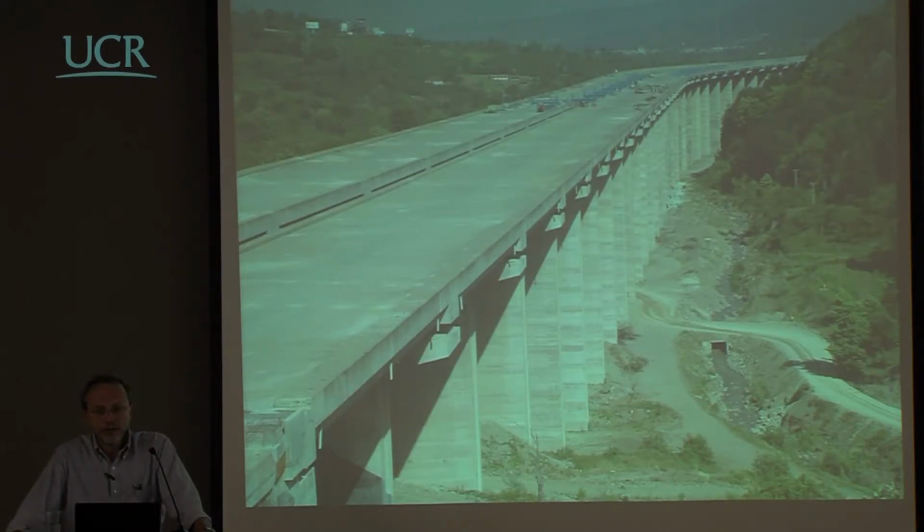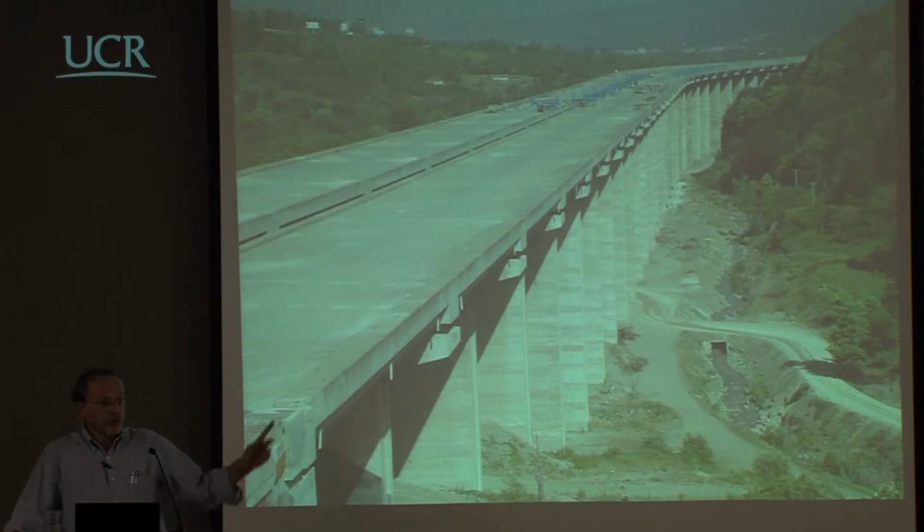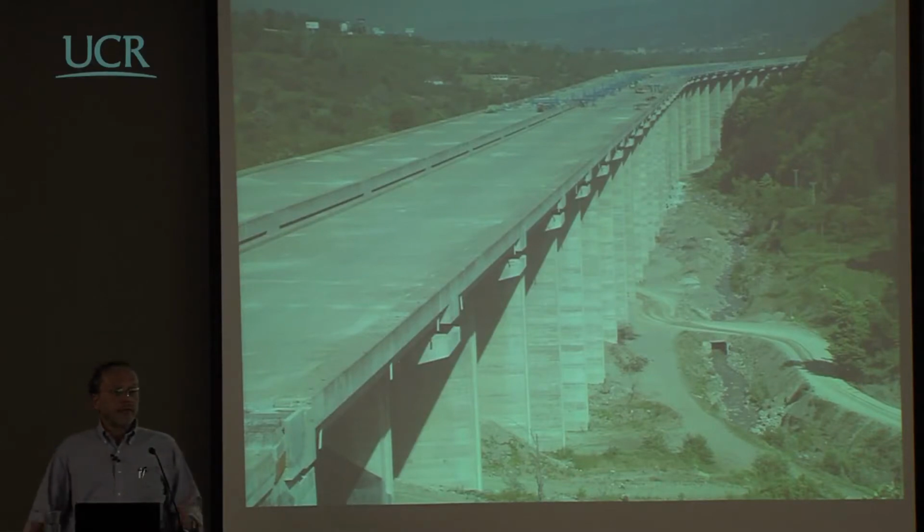The same year, later on in November, there was a second earthquake, which is known as the Duzce earthquake. And this earthquake was the one on this fault. And essentially, the fault was crossing the bridge at a relatively small angle, so it was not perpendicular. It was closer to being parallel than perpendicular. The angle was maybe 15 degrees or something like that. But it was just passing through the bridge.